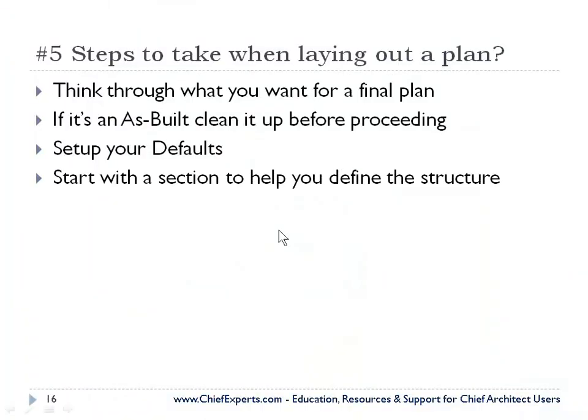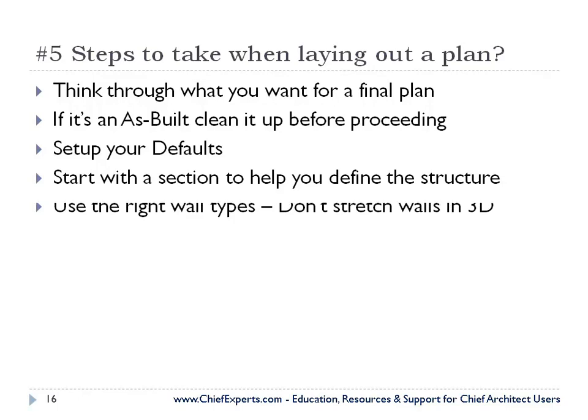Set up your defaults. Start with a section to help you define your structure. Again, we talked about that a little bit. Drawing the cross section first doesn't hurt. Use the right wall types when you're drawing a plan. Don't stretch walls in 3D unless you have no other choice.